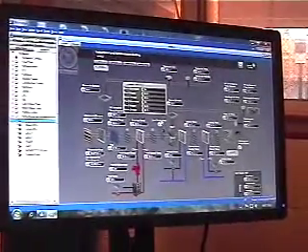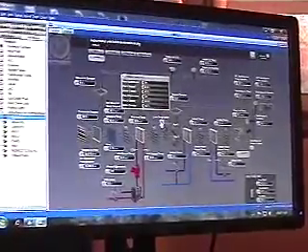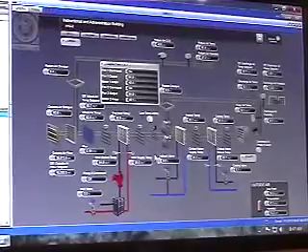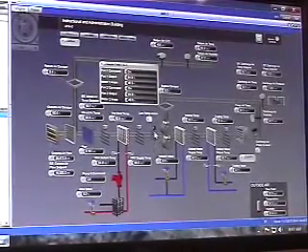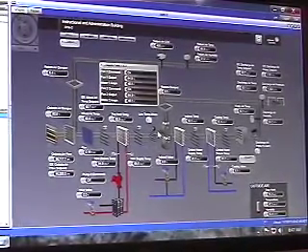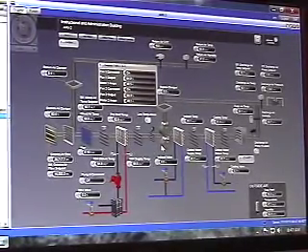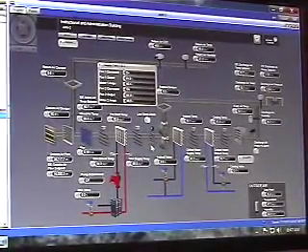Going through, you have your low temperature alarm, you do the same thing, it's just shrunk down. If it's red, it means it's an alarm. I believe there's 4 of these sensors for each air handler, so if any one of them trips, it will shut the whole fan system down. It is a manual reset, and it is a hard safety, so there's no overriding it in the system. You physically have to go and press the button.